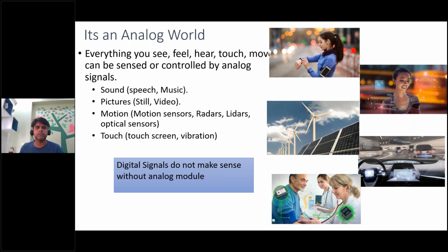Okay. So to make any electronic system or any subsystem usable, either for humans or for machines or industry or any place, you need an analog signal at an interface to make it work. Because any chip, be it the latest Intel processor, still needs IOs. It has to interface with the external world. It needs clocking subsystems. Digital circuits, you may have a very complex core, but they are still synchronous at heart. You need a clocking subsystem, which is a part of analog design. And you need power supply, because without power supply you cannot work, which is again an analog subsystem.